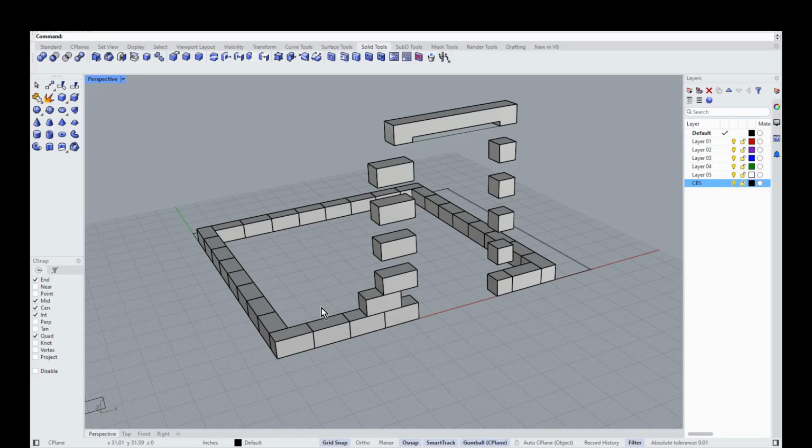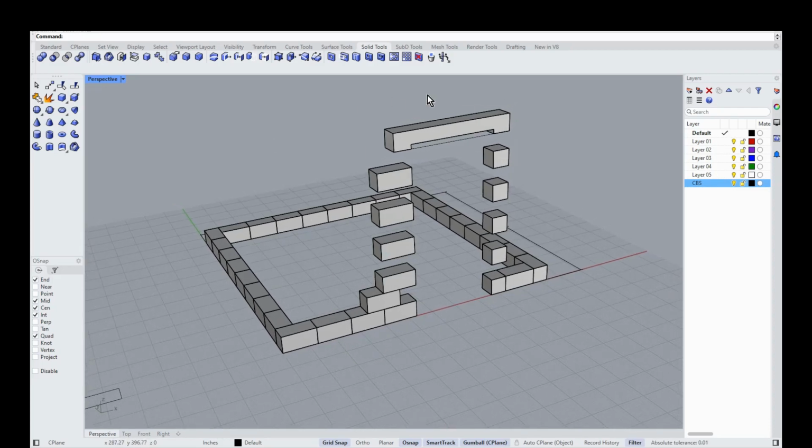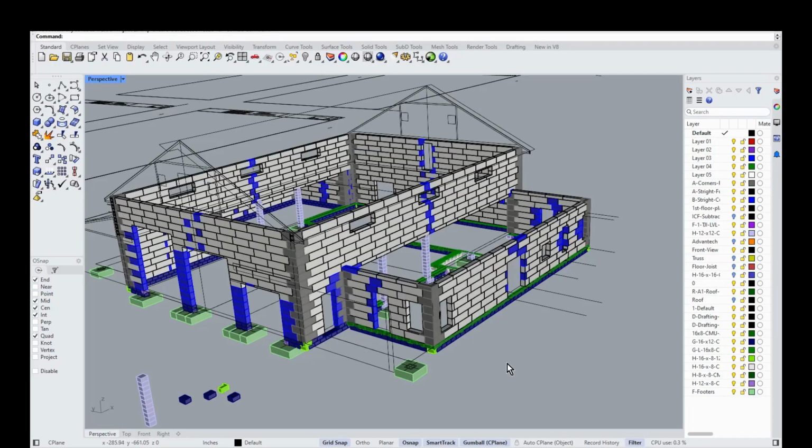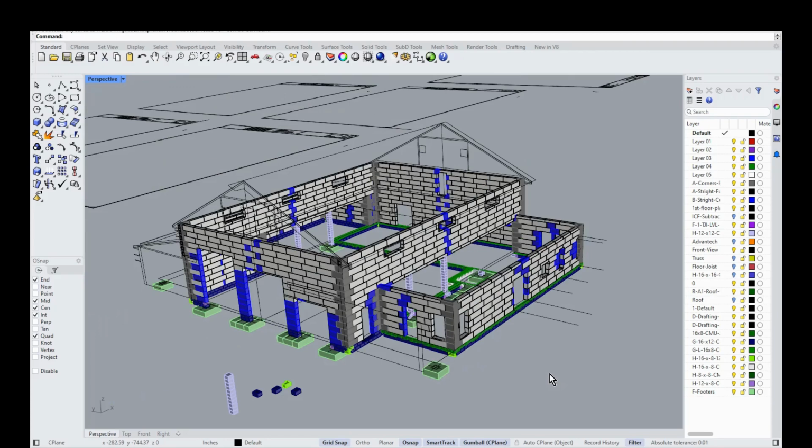For a huge cinder block house, you wouldn't do full 3D everywhere, just because of the low cost of cinder blocks, the ability to move them from site to site, and no lead time. But if you're hopping into ICF, that's where things get a little more scientific, because you could have tens of thousands of dollars of material short or extra on a job.